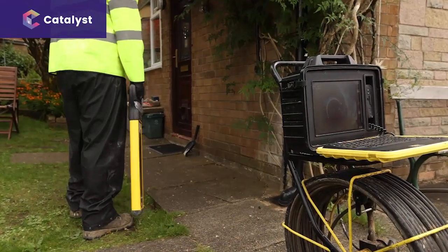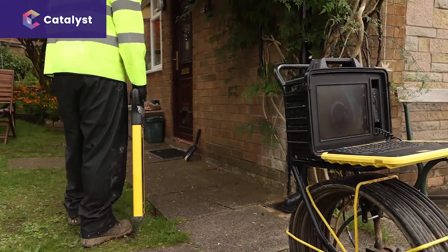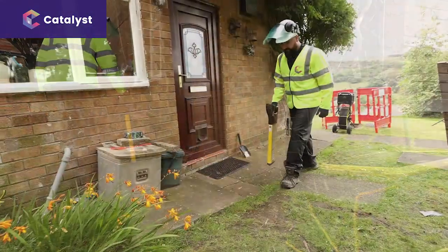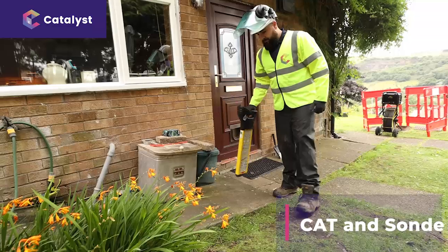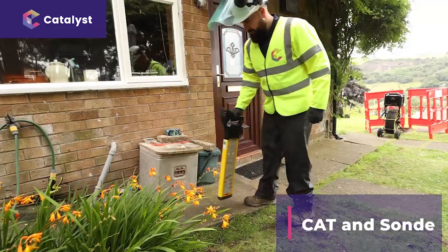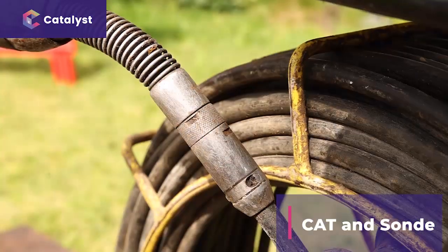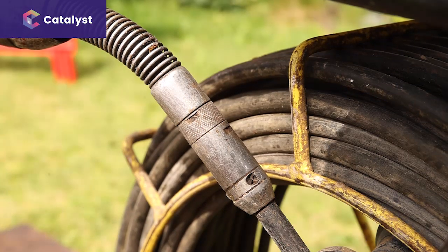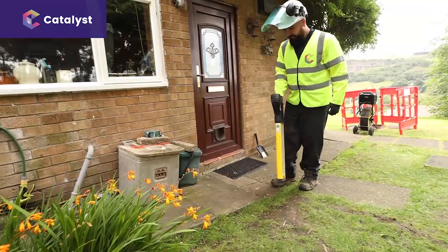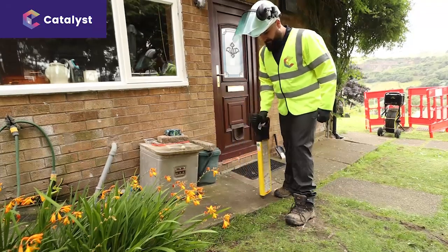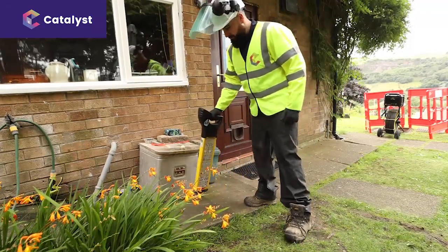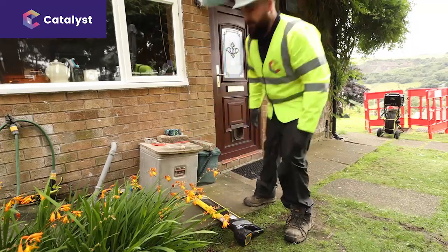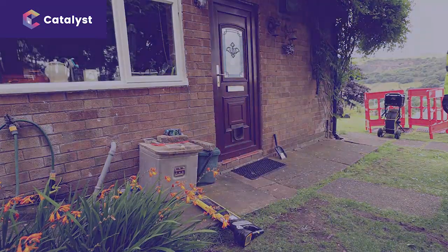Where excavation work is required, it is important to identify the location of the pipe repair. One way to do this is to use a cat and sonde. The equipment consists of a sonde, which is a radio transmitter, usually situated at the rear of the camera head in modern camera units. This sends a signal to the cat detection device, held by the drainage engineer. By sending the camera along the pipe, the engineer can locate the sonde above ground, so he can be absolutely sure of its location.